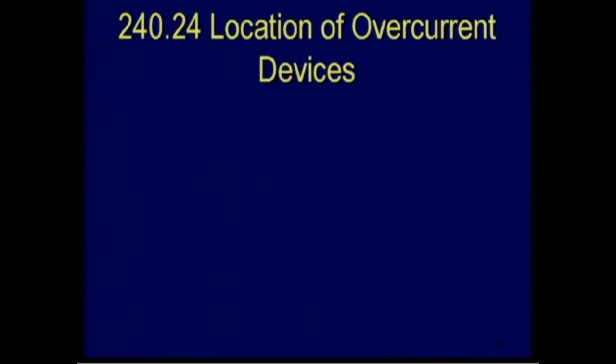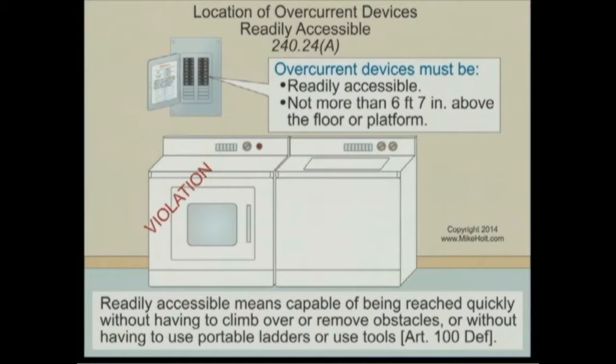What do they call that thing that you can just kind of go on the wire and you just kind of... A B-tap. What is it called? A B-tap. Yeah. I mean, are you kidding me? You just go into the enclosure and you just kind of screw that thing inside there, and it just bites right into the conductor, and without having to insulate it, without having to do anything. This is some cool stuff, but that requires understanding tap rules, sizing it. 240.24, the location of overcurrent devices. Kind of simple, easy stuff here.